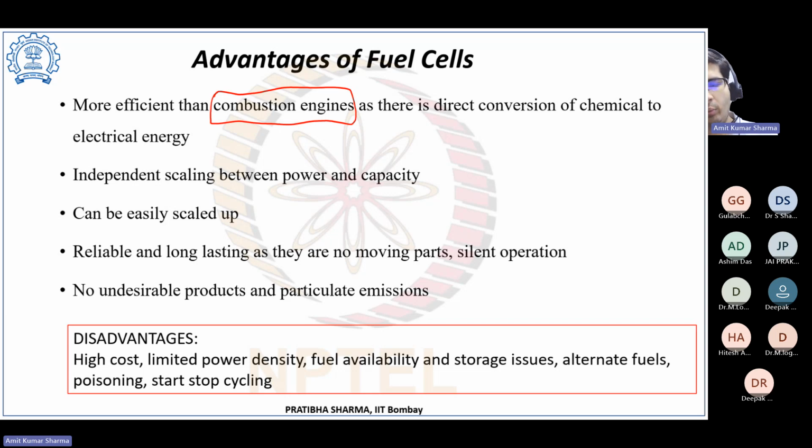There will be a reforming reaction and the exhaust heat will be very high. So you will put in a heat exchanger, make some investment, and use it to preheat the inlet stream. Suppose your inlet fuel and air are at 25 degrees centigrade. You use the exhaust stream at 900 degrees centigrade to preheat your inlet stream to a certain temperature, sometimes up to 700 or 750, so that you have to give only a very small amount of heat to maintain the inlet temperature.